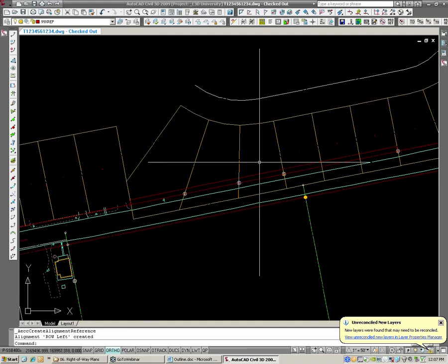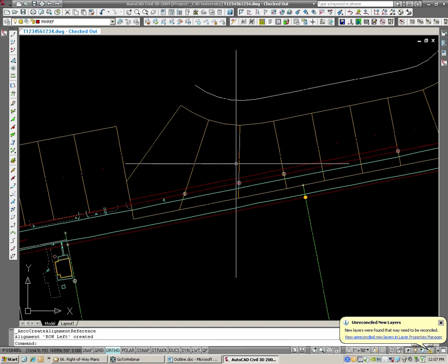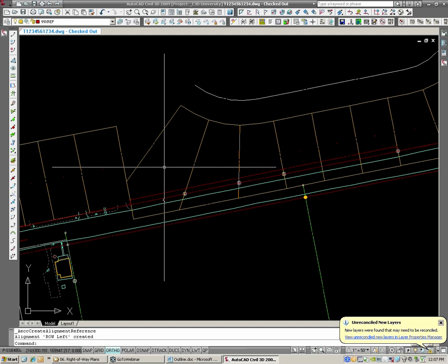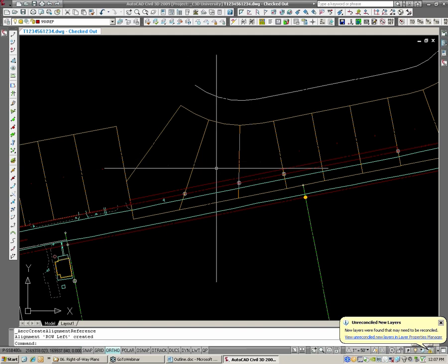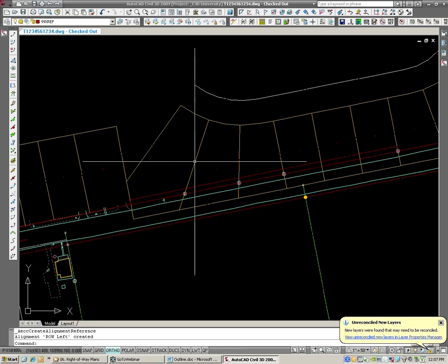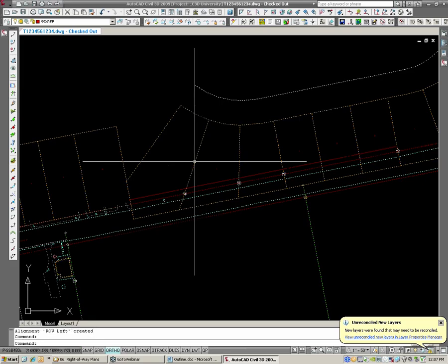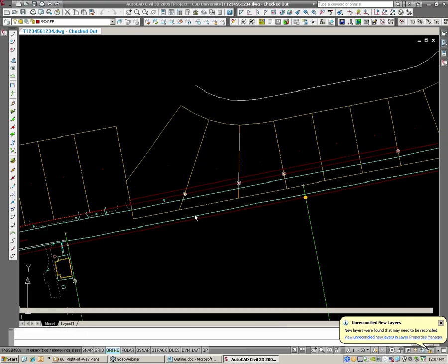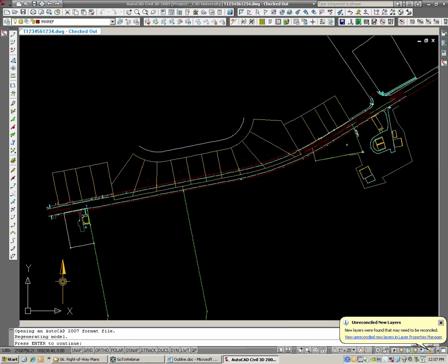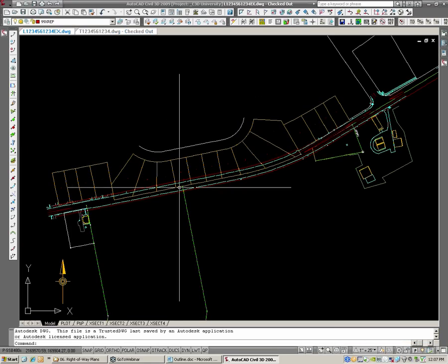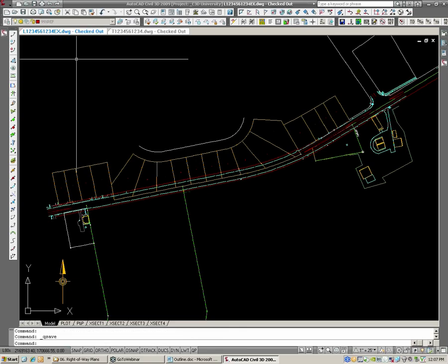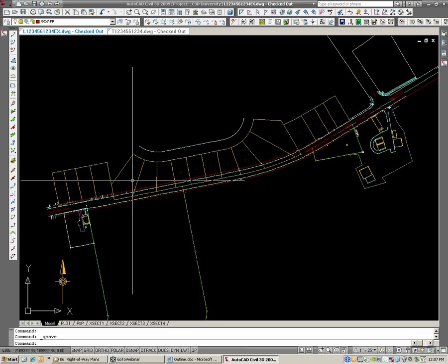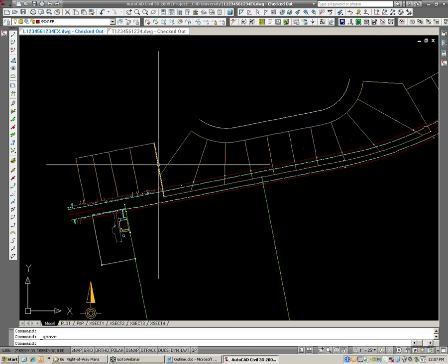First, knowing something about right-of-way plans, let's go look at some of the parcel numbering in the existing conditions file. Since I already have that file extracted in, I can just click on it, right-click, and hit Open Extract. And I already have that file checked out, I went through this before. You can see it right here opened up. And if I hit Save, you can see it's going to mark that as being checked out because it knows it's opened up. Now let's go ahead and look at these parcel numbering.